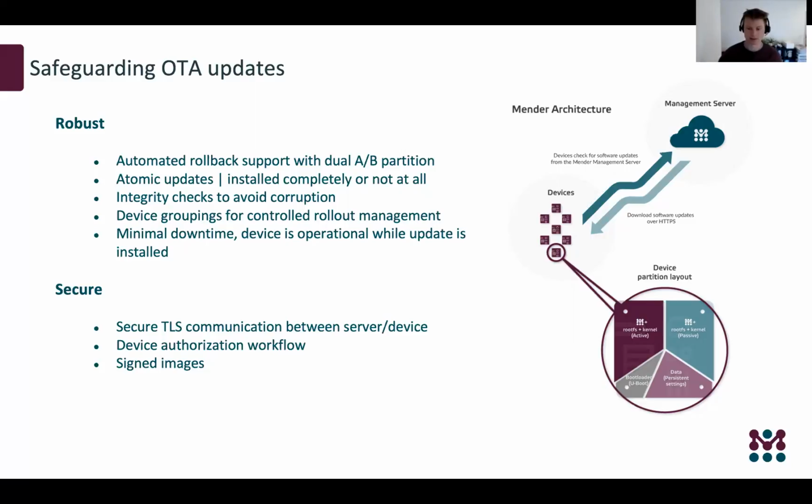So this is a pretty well tested and proven design in general that ensures that your device or product will always get back up online. So even if you lose power when you upgrade, you will have a working system because you're not updating the system you're running, and you will simply boot back into that one.